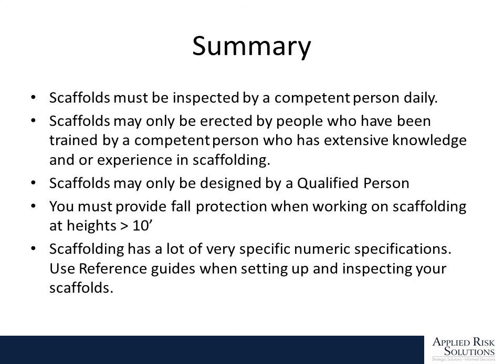In summary, scaffolds must be inspected by a competent person, each shift actually. And scaffolds may only be erected by people who have been trained by a competent person, and that competent person is somebody who has extensive knowledge and experience in scaffolding. Scaffolds may only be designed by a qualified person. And you must provide fall protection when working on scaffolding at a height of greater than 10 feet. And remember, scaffolding has a lot of very specific numeric specifications. Use reference guides when setting it up and inspecting it to make sure you don't miss anything.